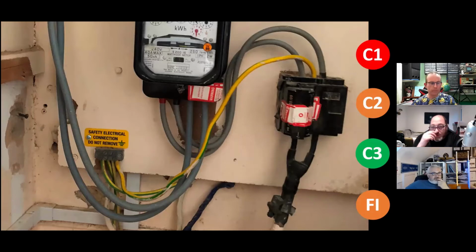I'm going to throw out my thoughts when I first saw this, because this is in my house downstairs. When I first saw that, I thought, well, that was a TNS. It's been converted to PME. If I did code it, it'd be C3 just to remove the clamp from it. But I had thermal imaging done on this, and there was a loose connection in the fuse carrier as I moved into the house. So they changed it for a GRP cutout, funnily enough, because it looks like one of those black phenolic cutouts.